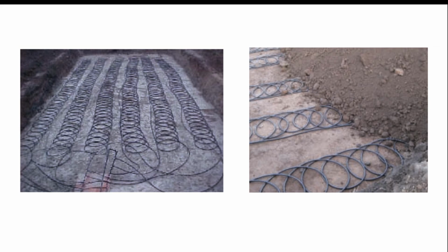A lot of designers have resorted to putting a perforated tremie pipe into the center of all of these loops so that if necessary, they can induce water into the loop field and retain or increase its thermal conductivity.